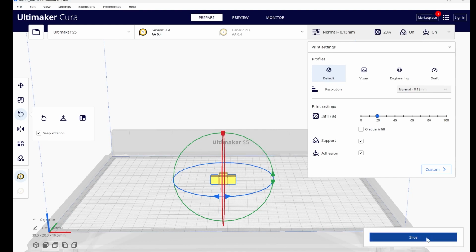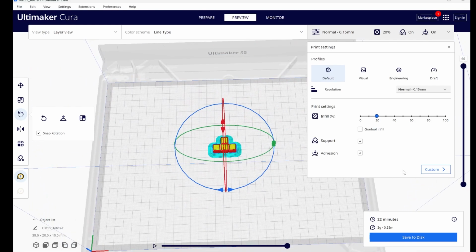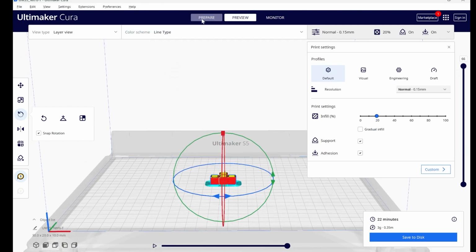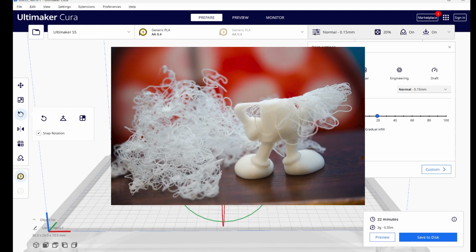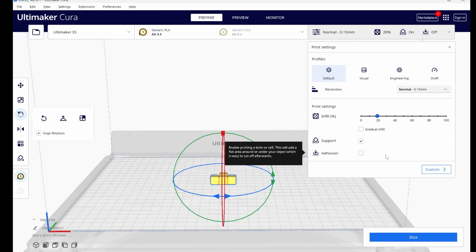Finally, you can add an adhesion layer to your print. This is a footprint around your object that will help it stick to the bed. Remember that the print material will contract as it cools, which could cause it to break away from the print bed or warp. This can lead to further issues like spaghetti prints. This is especially true for small or thin objects. Adhesion layers are generally not necessary for parts with large flat surfaces contacting the print bed.